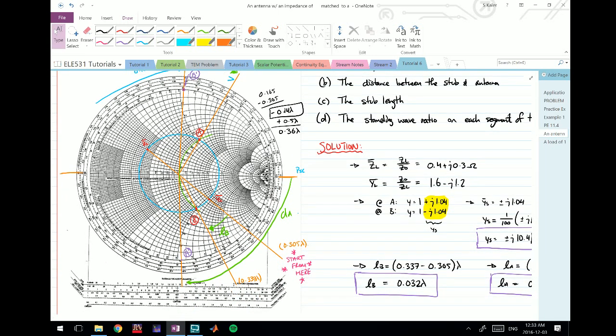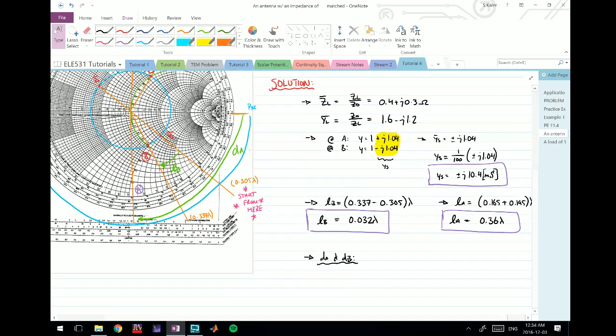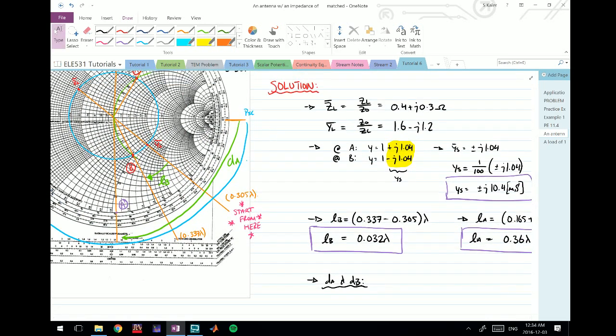And you see here, this is why I draw these lines on the outside, because this way I can go out and realize that I'm still at that same point, and so I know which point I'm lining up with. So that's dB. I should get rid of this so we don't confuse anyone. So dA is the first point we're going to find. On this side, we are at 0.25 lambda, always.